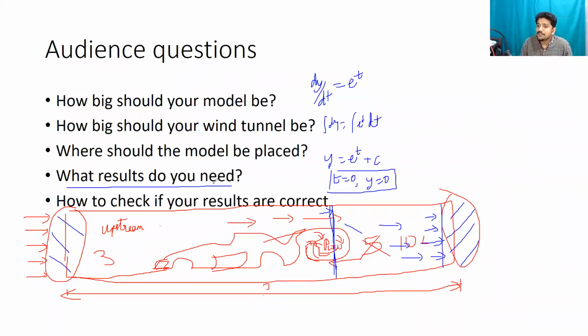Let me answer Sohan's question. So no boundary defined, low pressure area instead of a boundary. But Sohan, the whole idea behind doing the CFD is to determine how low the pressure gets. Remember, on the back side of the car, the pressure is lower, okay? So it's called PL. And the front side of the car, you have your stagnation pressure, correct? So this PS minus PL is ultimately going to be your pressure drag, which is what you're trying to determine. So without doing CFD, you do not know what this PL is. So there's no way for you to guess that.